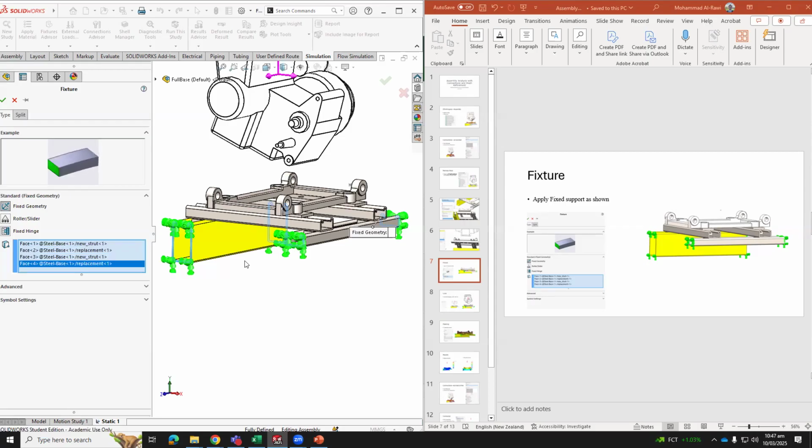And you have vertex as well, but it must be faces. I must see faces here to ensure I have selected correctly. If I see edge or vertex, it means delete and reselect the face. Because the software starts feeling heavy now, you can see it. Yeah, face 1, and then go and select the other faces.